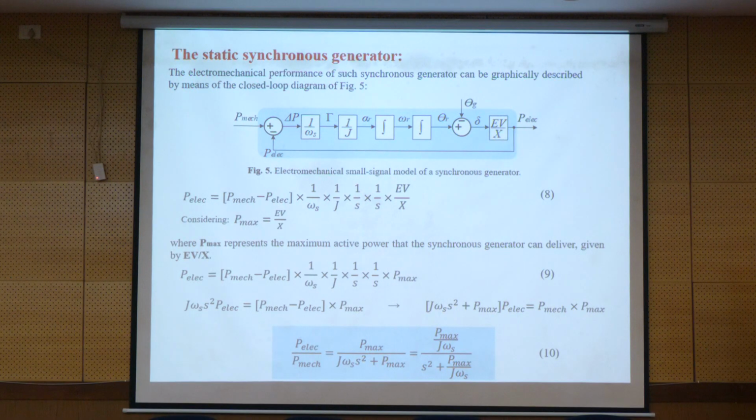Yes, if it is a small one. But when we are talking about a short circuit in a system, then it could be different. For example, if you are going to consider the fault ride-through capability of the converter-based generator, we don't go through small signal analysis. We have a different perspective. You cannot say delta I is this one, because we don't have small delta I changes. We have big changes.